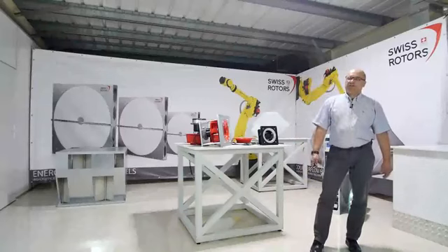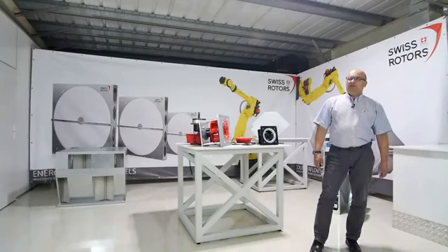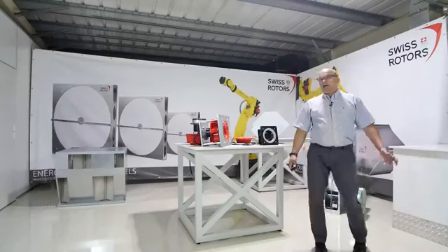the size of the fan is very small, so it's much easier to exchange this smaller fan than one big fan. Usually you need to have a support, because there is a very heavy motor. You need to organize and be prepared for this exchange, and then of course the air handling unit will be out of service for quite a long time, some hours.